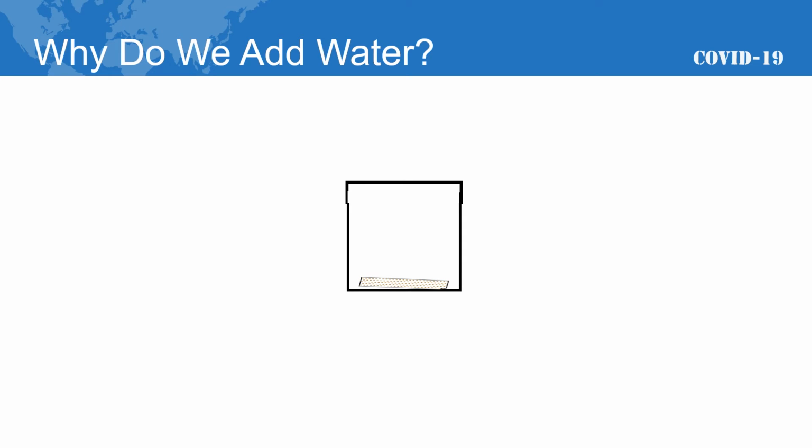You might be wondering, why do we add water inside of the chamber? It's because we would like the humidity to remain constant. However, after we increase the temperature, the humidity of air decreases. But if we add water to the paper tissue, then the evaporation of that water at high temperatures will cause the chamber to have a constant humidity. Determining the mass of the water added will also be an objective for the experiment.